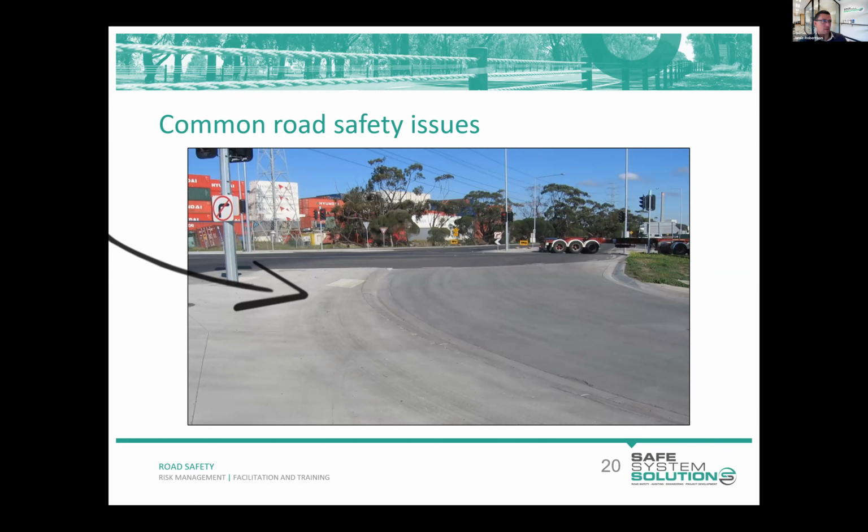It's also been suggested to me that excessive speed is part of the problem here. So there's a risk to pedestrians when vehicles encroach on pedestrian areas such as this. I'd suggest someone standing here is perhaps not so much at risk as someone on the other side of the road. The direction of travel at this location is towards us, so someone standing on the island here at the tactiles would be in view of an approaching motorist, and you would hope that they wouldn't continue on that path if someone was waiting there.